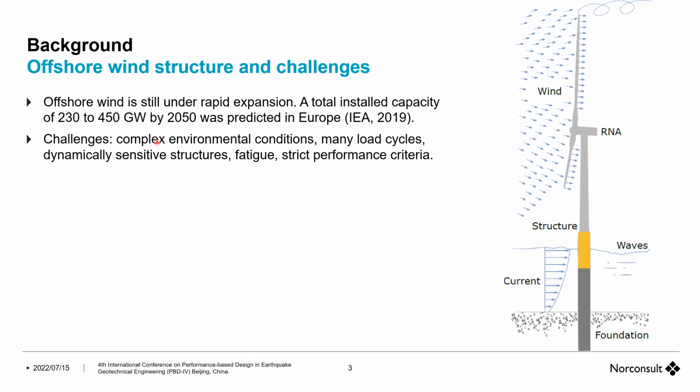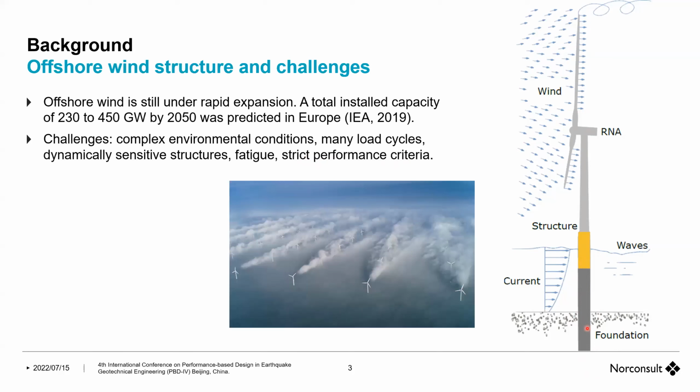There are challenges: complex environmental conditions. You have wind, you have waves, and of course many load cycles, millions and millions of load cycles. They are dynamically sensitive structures. Fatigue is an issue. And of course, for us geotechnical earthquake engineers, there are strict performance criteria with respect to the deformation of these structures. And this gives you a picture of the type of loading.